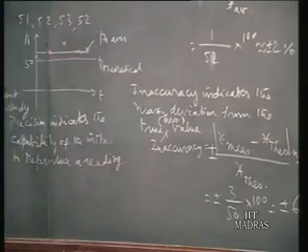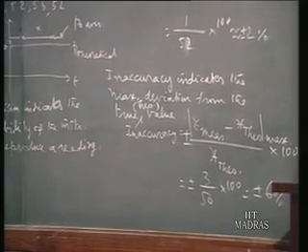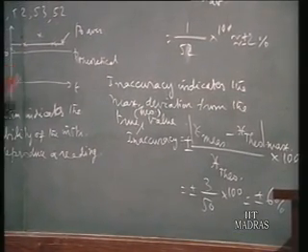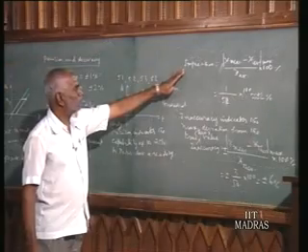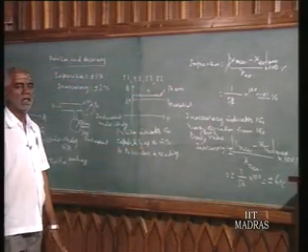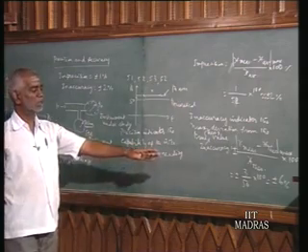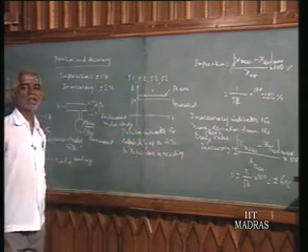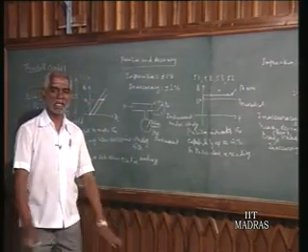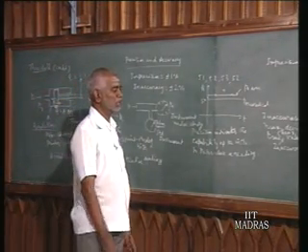Now you note the difference. For the same instrument, you got two different quantities. From this experiment, the instrument has an imprecision of 2% and an inaccuracy of plus or minus 6%. This example makes it very clear that imprecision and inaccuracy are not the same. They are two different things.